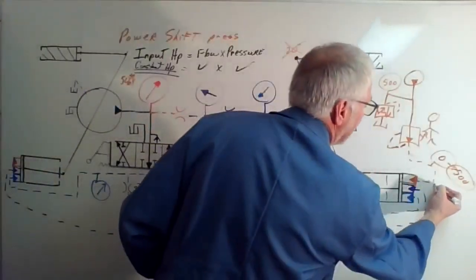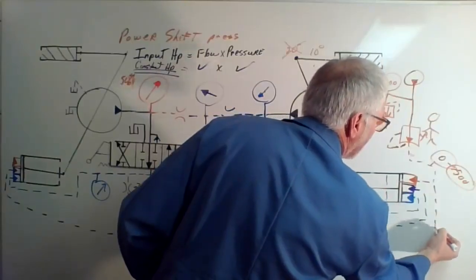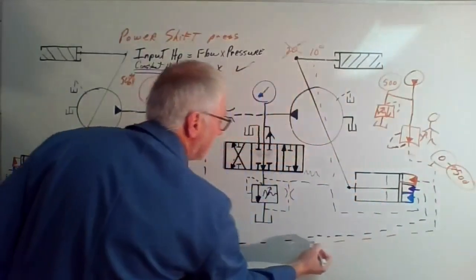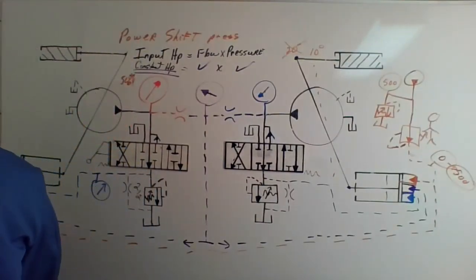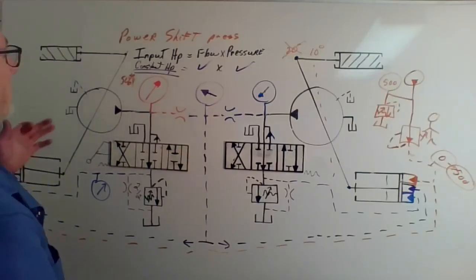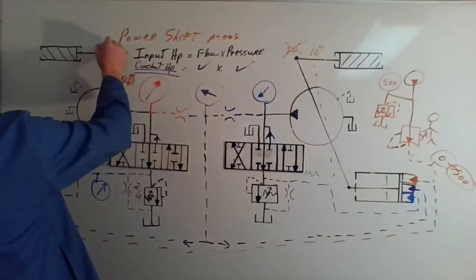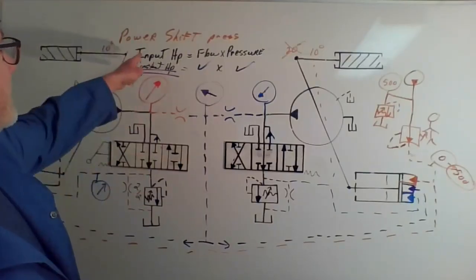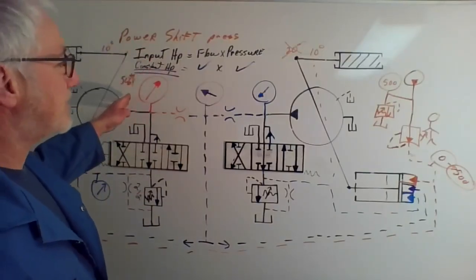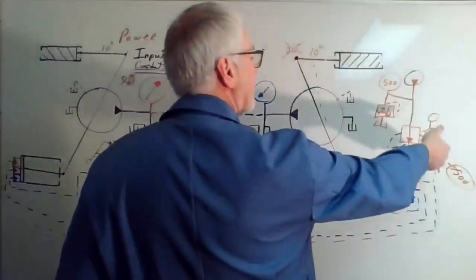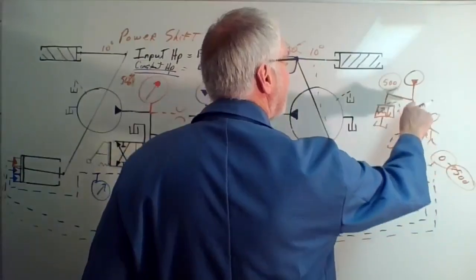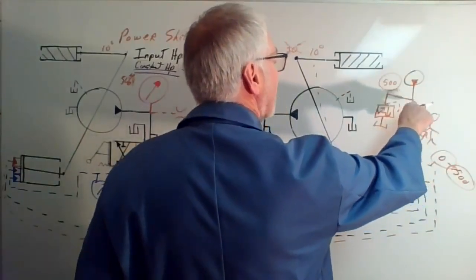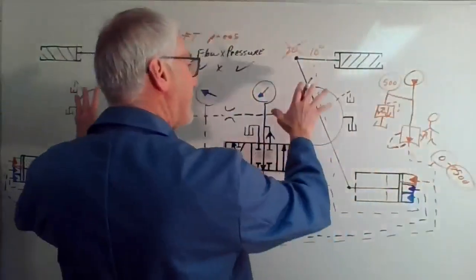And by the way, because you're going to try and control the maximum horsepower, we're going to send it all the way over and control both pumps to physically now only produce 10 degrees. You wanted to turn this constant horsepower down 50%? No problem. The operator has a little dial in the cab and he hydraulically adjusts the dial, and what he doesn't realize is you're using this lovely pilot system, which is really the control for the main pumps.